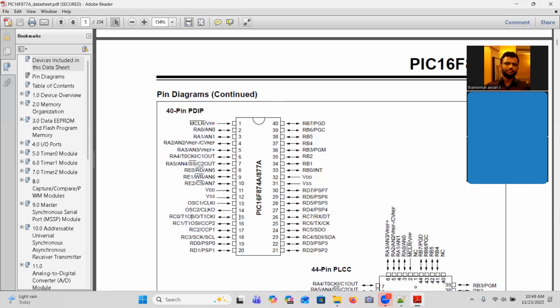That makes sense now. So when we connect this crystal oscillator, the remaining clock generation circuitry is internal to the microcontroller. It will generate a clock and use it. If you decide not to connect the crystal oscillator alone, and you don't want to use the clock generation circuitry of the microcontroller, you have an option to supply a clock generated by an external clock circuitry, which includes an oscillator.